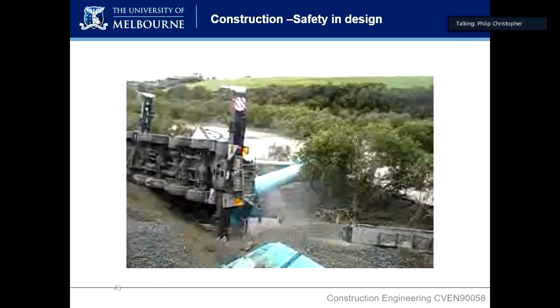In talking with a lot of these construction companies, so Delta Group or any of the other tier 1 companies, the focus on these outrigger locations for the cranes is really critical, and it actually forms part of the design process to such an extent that often what will be done is a pile will be located just for that crane's outrigger. So you might go out on site, put in a CFA pile just where the outrigger is going to sit, so that outrigger can sit on a nice, strong surface and not have any risk of that. So obviously the assessment of these conditions is really important.